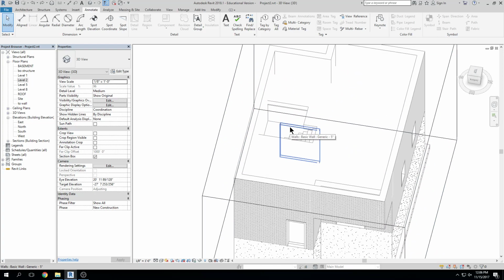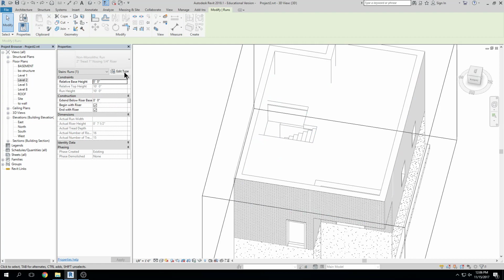So how do you make the risers just easy to be not inside of the wall? You change that setting in the stair. You mean the stringers? No, the railings? Well, it just generates them according to where the stringer is placed. So if you chose that no stringer option or the closed one, the railing would host to the stringer, and it would host inside the stairway instead of with the stringer inside the wall. Does that make sense what I'm saying?